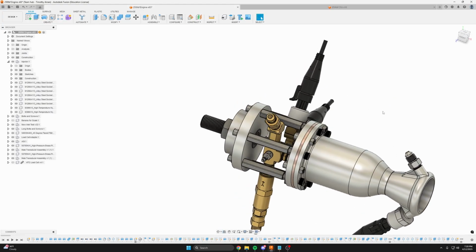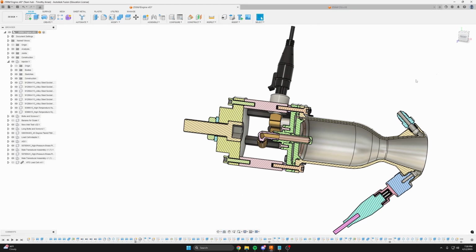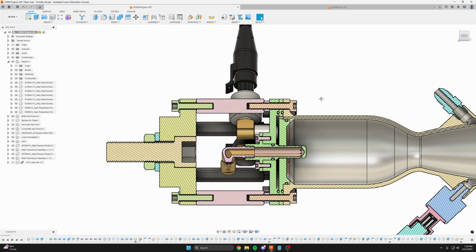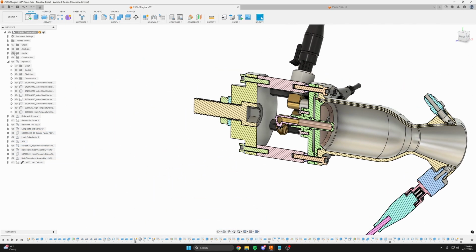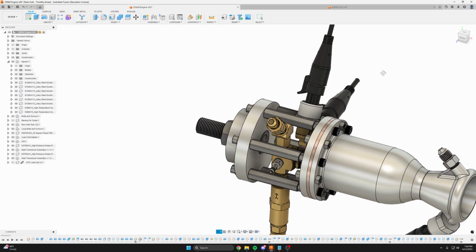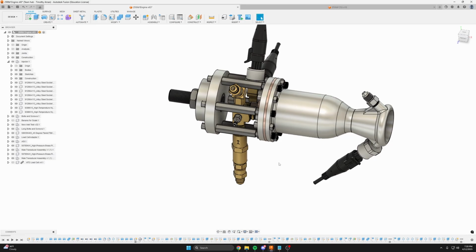So we chose to use gaseous oxygen as the oxidizer for the ASI, even though we're using nitrous oxide as the oxidizer for the main chamber. Because we're pulling the liquid phase nitrous as the oxidizer for the main chamber, it is possible to pull gas phase nitrous from the same tank or from a different tank, which could work well for you. But we chose to just use gaseous oxygen, and that has proven pretty reliable for lighting.